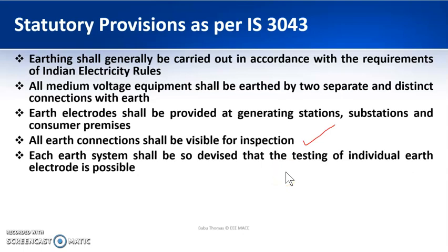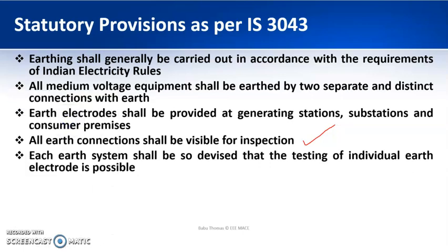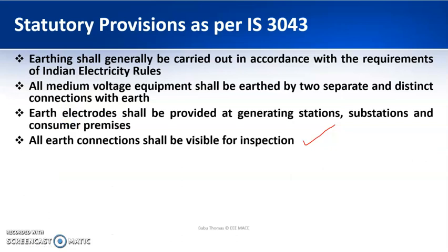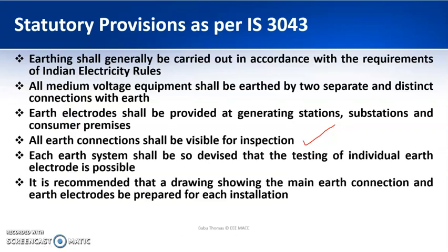And the earthing system shall be implemented such that testing of the individual earth electrode is possible. So at any instant of time, you need to test your electrode. That provision should be available, and there should be a drawing of that particular earth system.